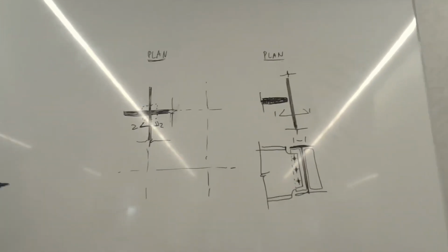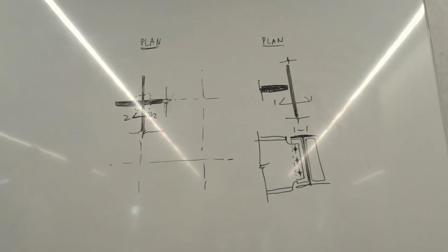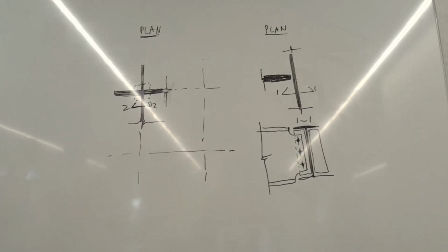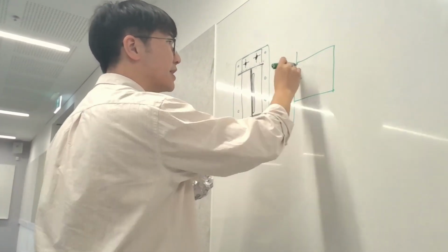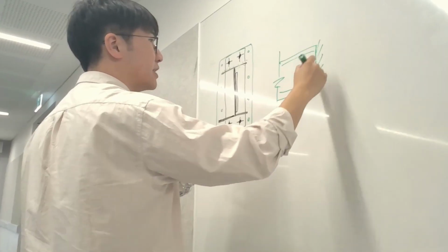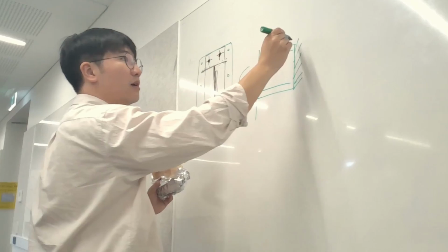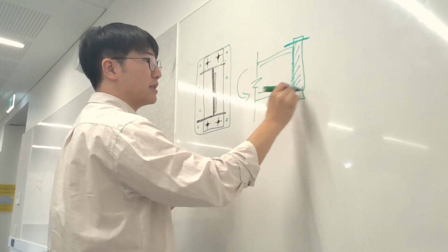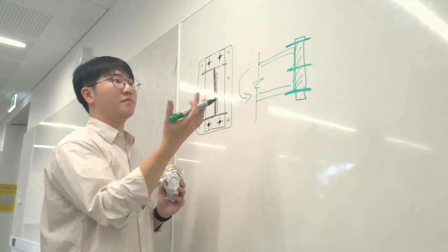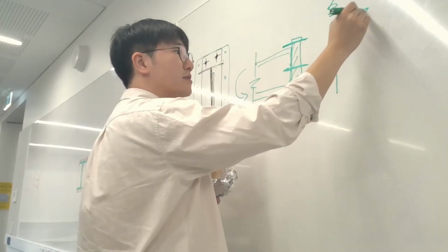Yeah. The difference really is that those bolts are in shear. So if you imagine the downward forces, it's causing the bolts to basically split apart through shearing. Whereas these ones, if you imagine a moment, so that's the I-beam, and then you're connecting there. Pretend there's a moment that causes this. That's a plate, and you've got bolts like that, for example. This is inducing bending, and so the stress distribution actually looks like this.